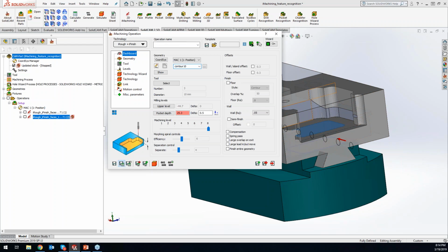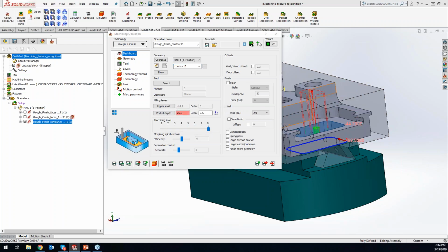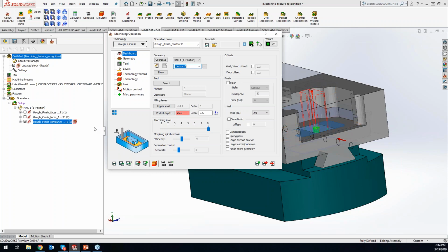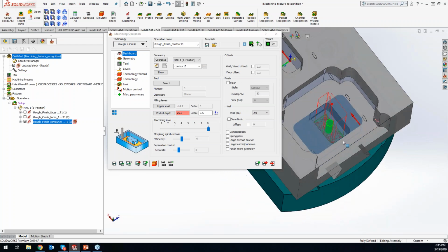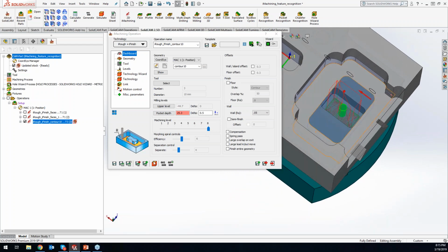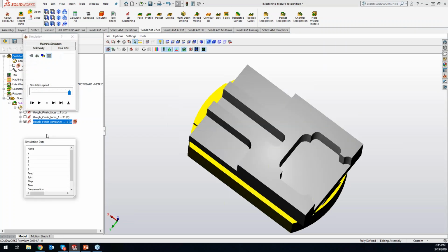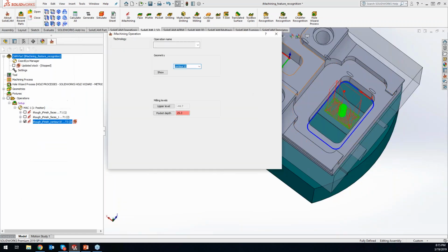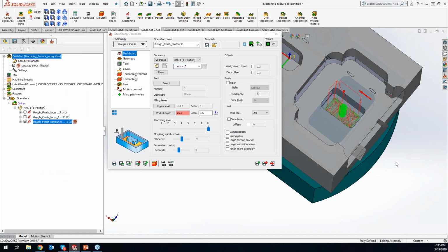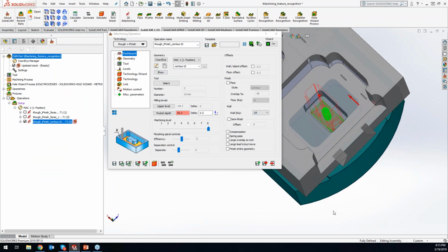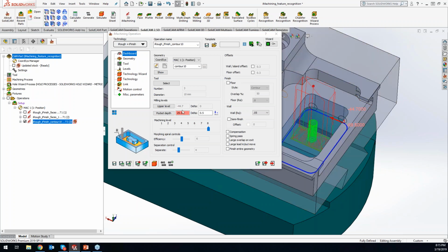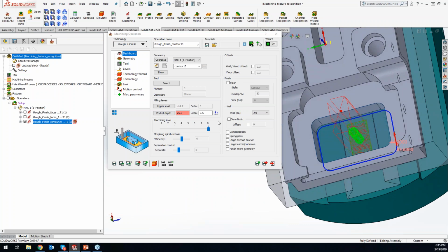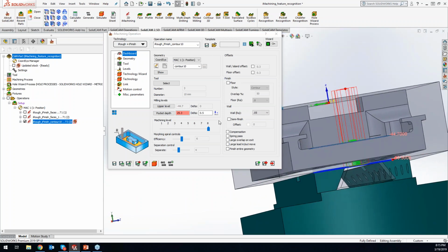So from right here, if I do save and calculate, you'll see that it's machining down in there, and it's going to get that material out of there as well. One second here. Let's do a quick simulate. And my chain is not going to the entire diameter here. I think you picked the wrong spot on your fixture. Oh, did I? Because of that dovetail. Yeah, it's trying to stay in between that dovetail.